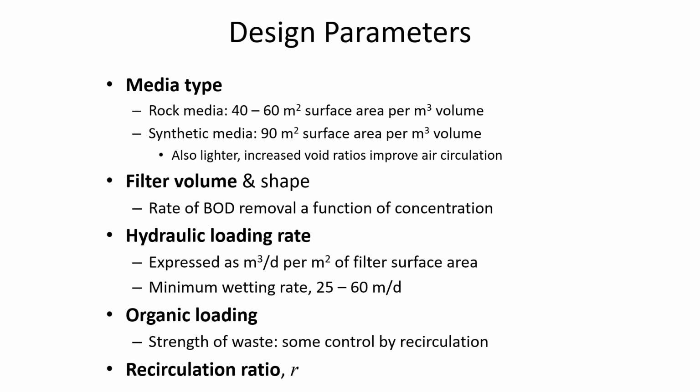Trying to decide how big the trickling filter should be and its shape is one of the factors that they'll think about. The hydraulic loading rate is trying to make sure that you keep the slime from drying out, applying enough water so that you don't have it prematurely sloughing before it's a thick enough layer. So there's a minimum wetting rate that can be difficult to maintain at night if you don't have a flow equalization basin. Flow equalization basins can also give you some control over the organic loading to keep that more constant